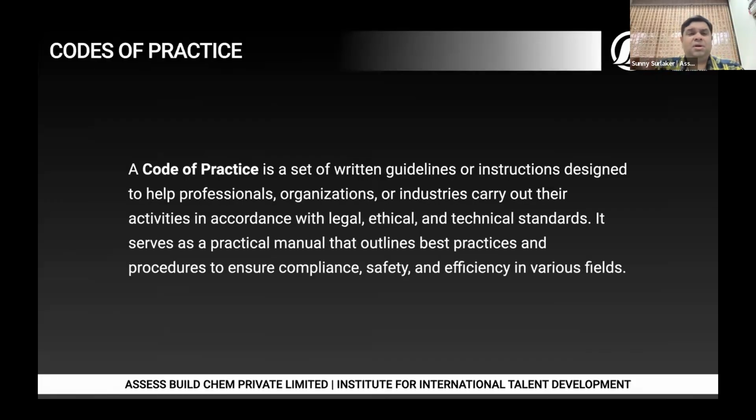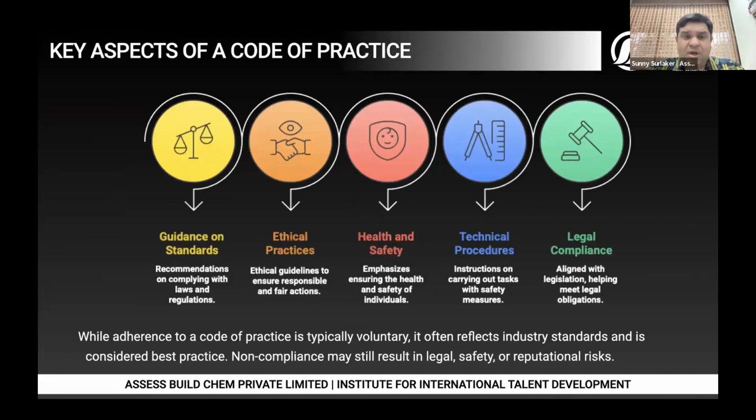A lot of people confuse this with codes. There might be guidance codes that guide you how to do a particular process. For example, there are codes on execution of basement waterproofing, say BS 8102 or 16471 in the IS codes. So they talk about different steps that you need to take to do basement waterproofing, for example.